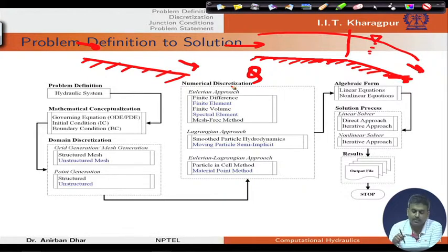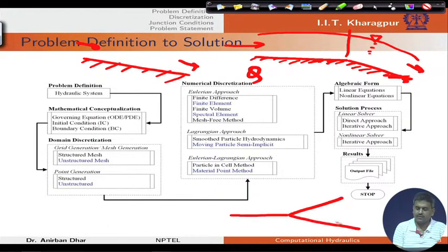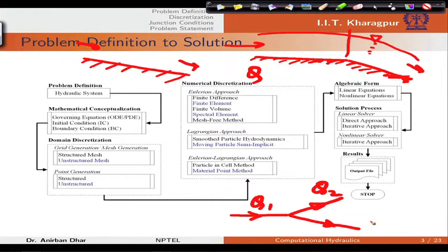and the only variable is y, or flow depth. But if we have multiple channels, let us say we have this kind of situation where flow is coming from here and there are two channels at the downstream end. Obviously, if the flow here is Q1, and in one section it is Q2 and in another section it is Q3, obviously this Q1 should be equal to Q2 plus Q3.